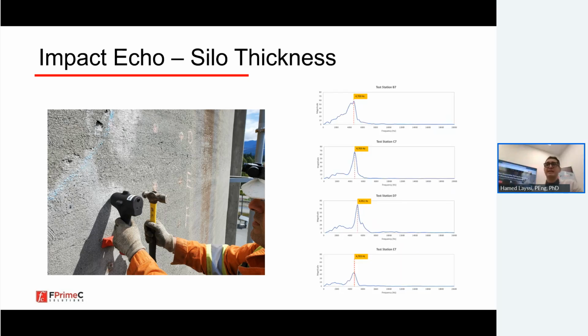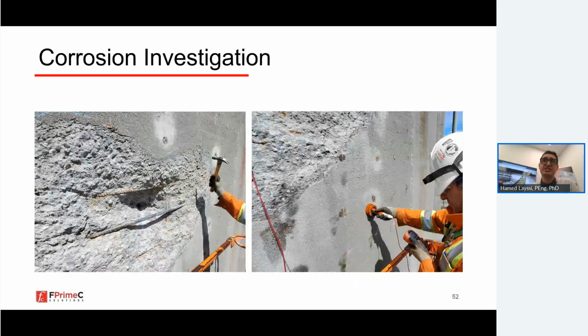So these are the impact echo results that we obtained on this element. As you can see, a beautiful singular peak in the impact echo, very much associated with the back end reflection. So we were able to identify that we only see this back end reflection, with no higher frequencies that might be associated with delamination. With this test, we moved into the second stage of the testing.